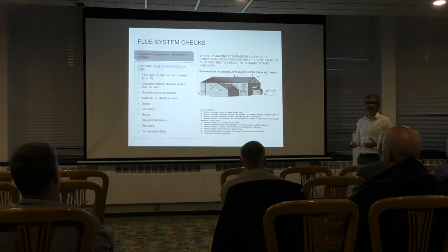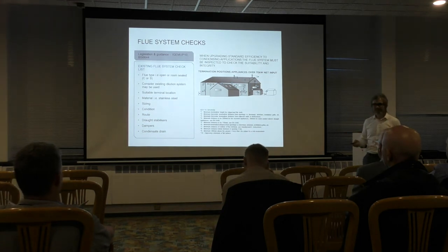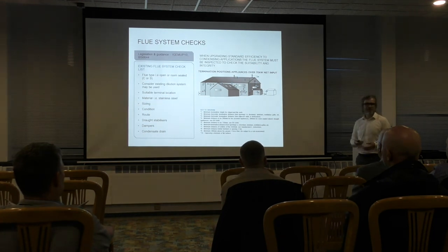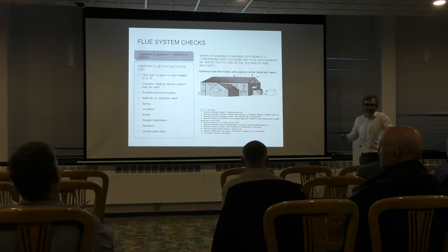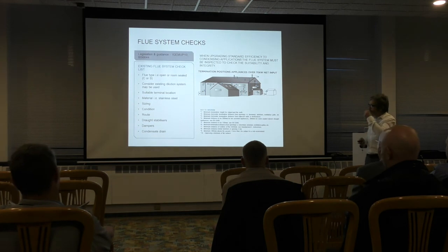Chances are it would have been, because those boilers were premix boilers anyway, and they were the same output, so you probably wouldn't have had an issue. But you can't say that to a client: chances are your flue will be okay, we'll wait and see once we've installed it. It's not how it works. So you just have to be aware of the route. Draft stabilisers and dampers.